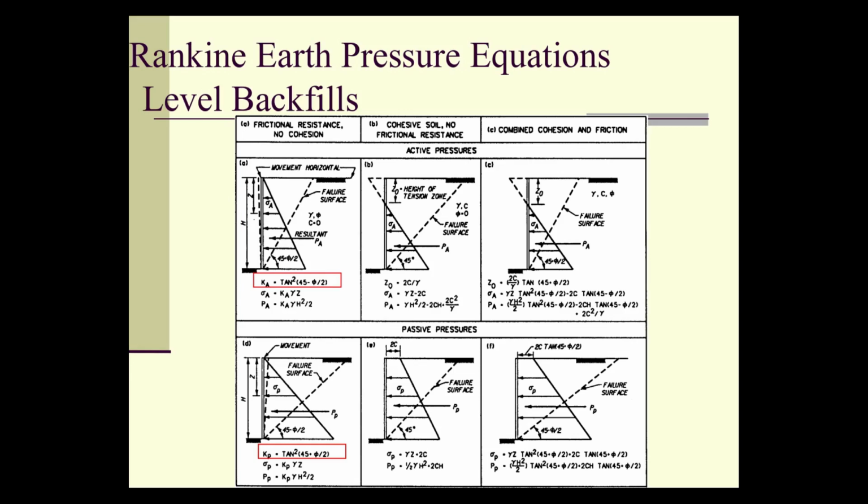But if you were to excavate and then put the wall in, however you do it, a purely cohesive soil will be able to stand on its own from the top down to a certain point. Well, that's the height of the tension zone. The theory tells me it's supposed to be in tension. The reality tells me that, no, it's not going to be in tension.